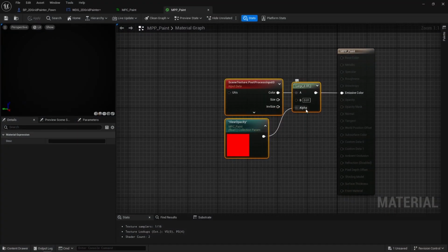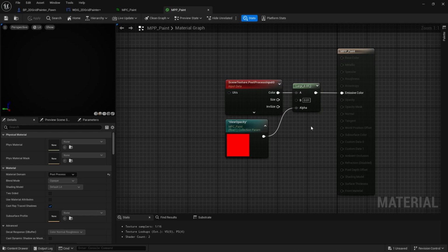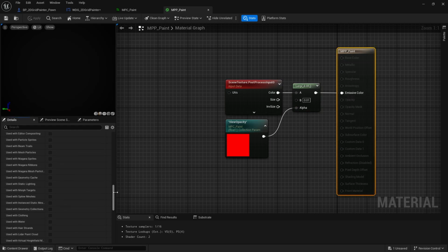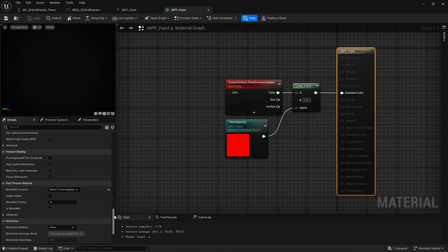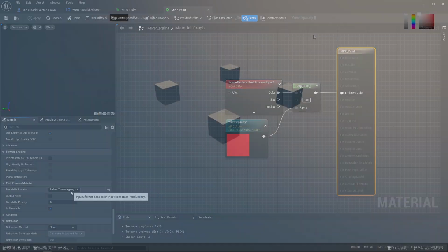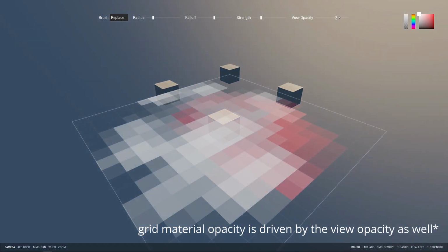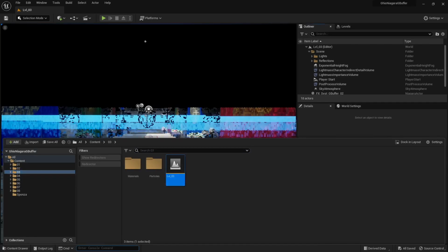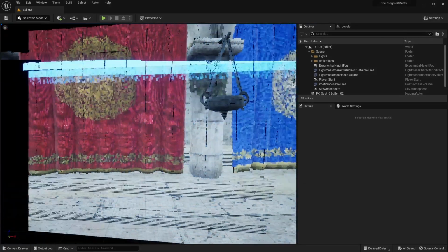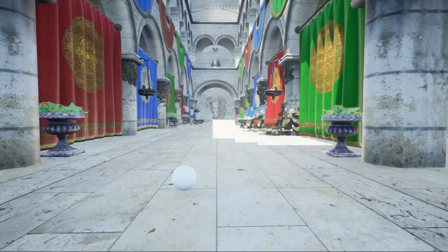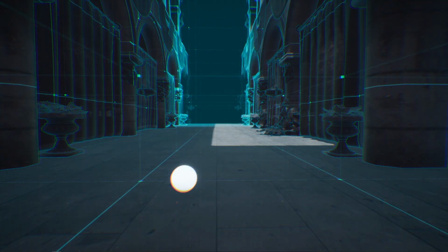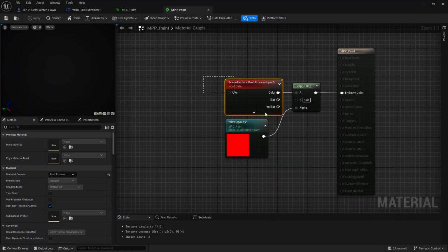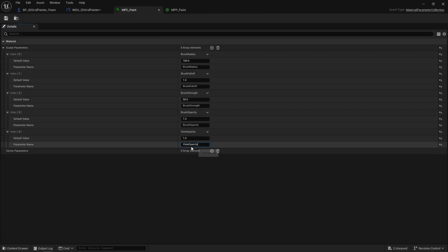That plain color should in theory be displayed on top of everything. Well, yes, but that's not necessarily true for translucent materials. A post-processed material can be drawn before tone mapping, meaning before translucency is rendered. So you get to see translucent materials rendered on top. That's a cool little trick I already explained in my Niagara gbuffer introduction video, but also in my post-processed VFX tutorial. Anyway, that's how I built the view overlay feature.